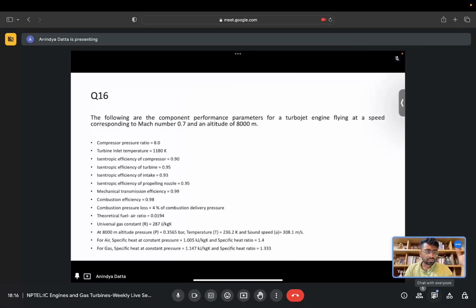Over the last two lectures we have also become acquainted with the idea of stagnation temperatures, how to draw a TS diagram with stagnation temperature and interpret the data from that, how work is defined as proportional to the stagnation temperature differences, and all those things.